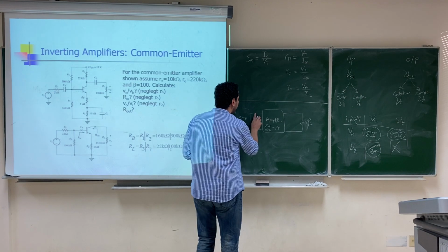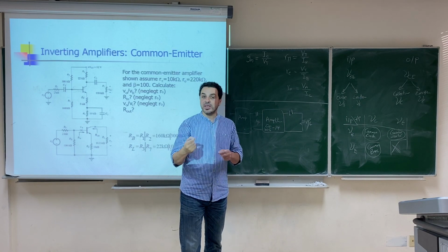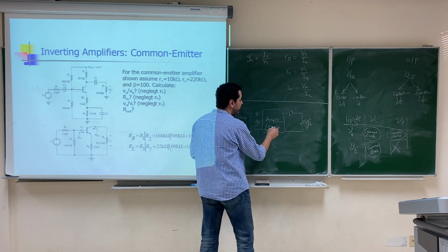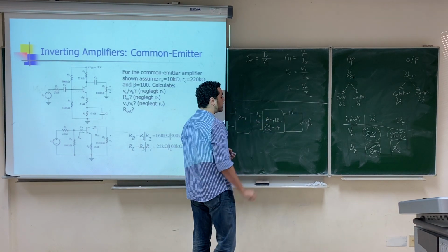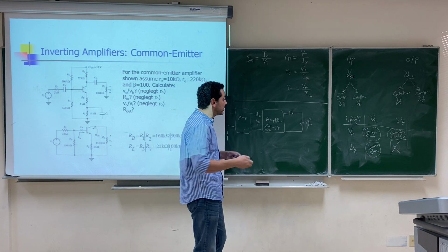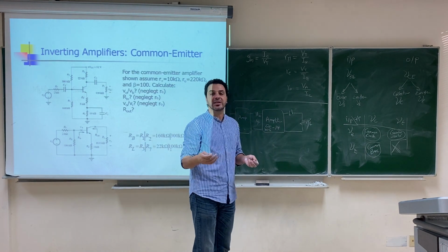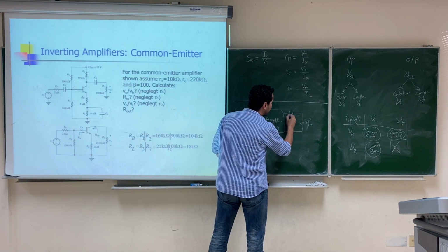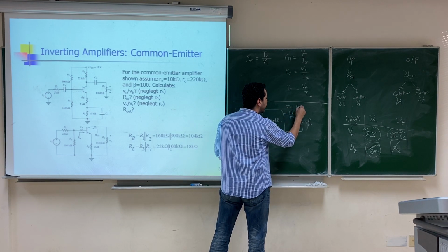They connect something called coupling capacitors. With respect to the DC, we know that a capacitor is an open circuit. So for the DC bias point, if you look at this capacitor, you will see an open circuit. While with respect to the AC, and this is what is important for the amplification, these capacitors will be on. And for simplicity here, we'll consider that for AC, the capacitors will be short circuit. With respect to the DC, they will be open circuit.